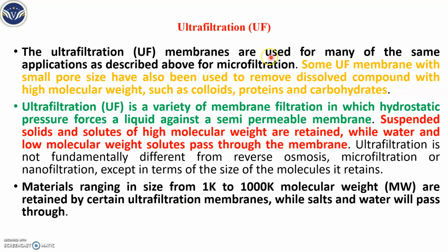Now, what do you mean by ultrafiltration? Ultrafiltration is the same as microfiltration, but here the pore sizes are a little bit smaller. It can remove dissolved solids of higher molecular weight. Here a hydrostatic force is applied against a semi-permeable membrane, so suspended solids with higher molecular weight are retained.